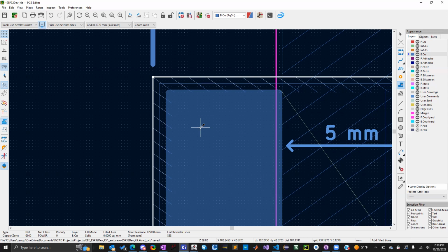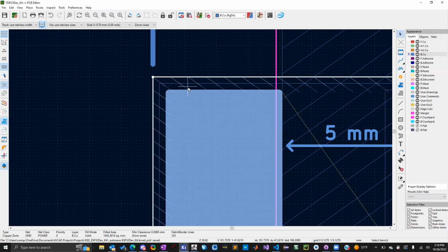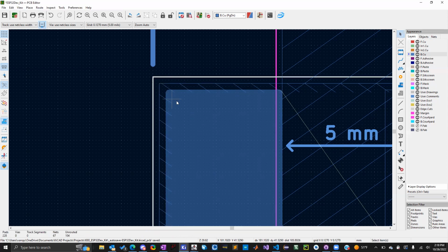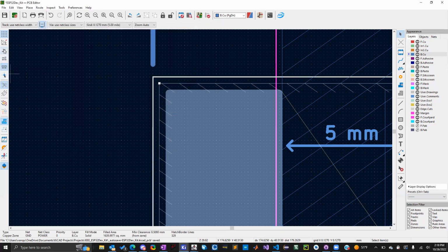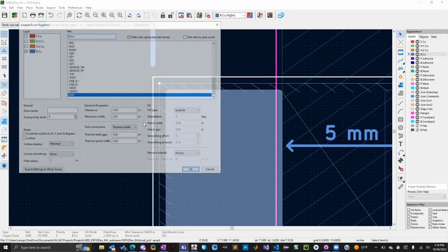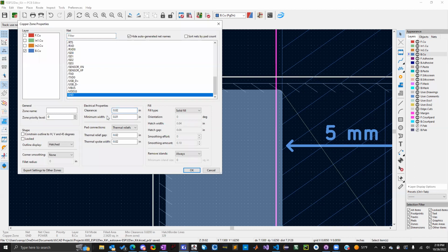Sorry about that. Somebody was having an issue. So that shouldn't have been an issue. I think what the problem was is you had some type of clearance setting that was such a large clearance that the entire board just had no copper, because the clearance from everything would have meant no copper on the back of the board.